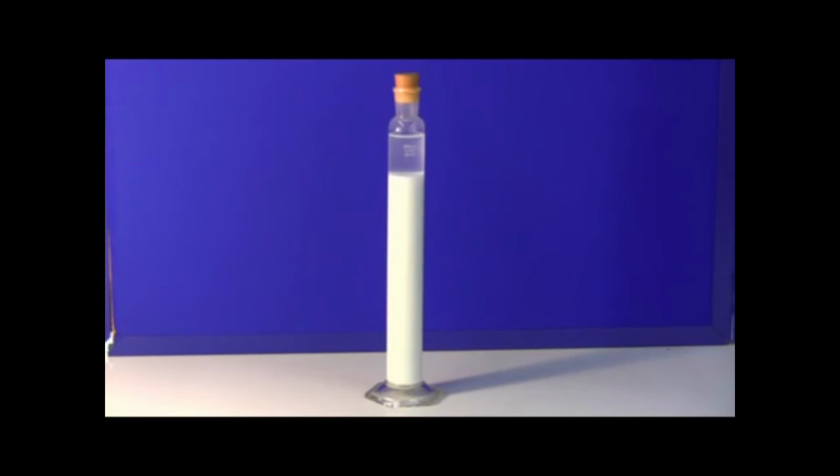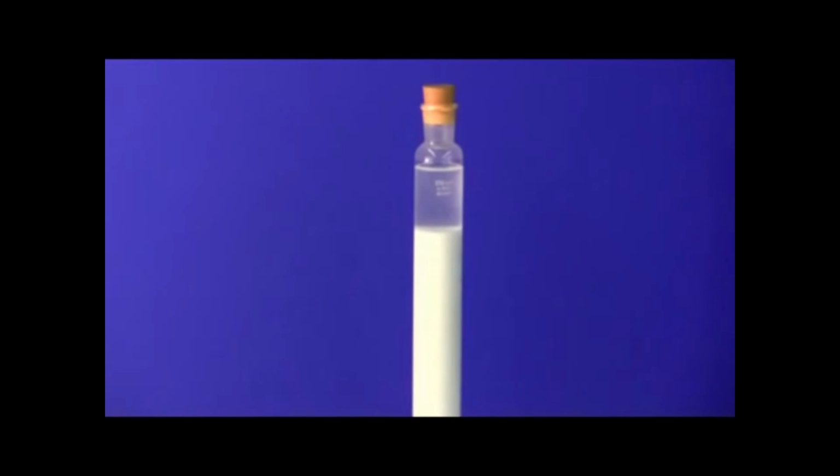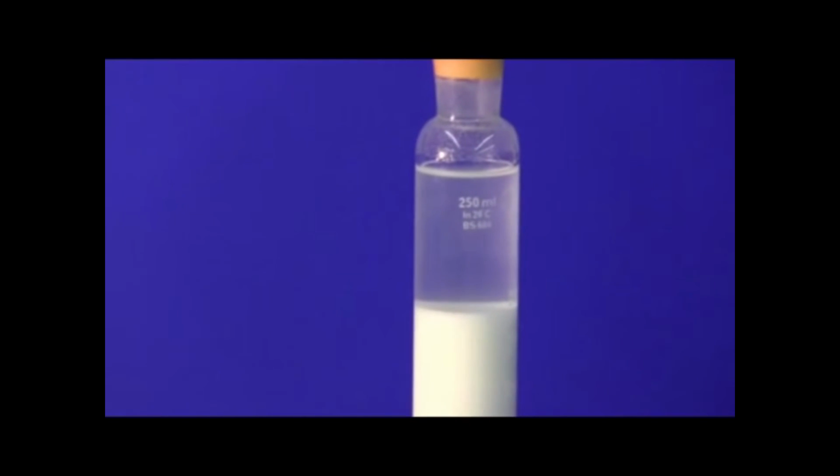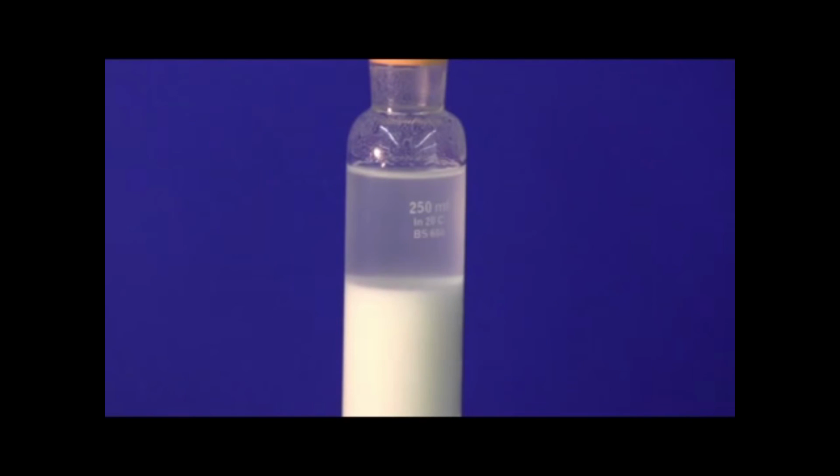And you can see there was an interface, and if we zoom in a little bit we can probably see that interface a little bit better. Here we go, there's another shaking up and settling, and you can see the interface quite clearly now. The supernatant liquid is not completely clear, but it's not bad. There's just very few solids left there. And if we were to plot this against time, we would see that it had a straight line and eventually a curve, and then when it was fully settled it would just become a plateau.